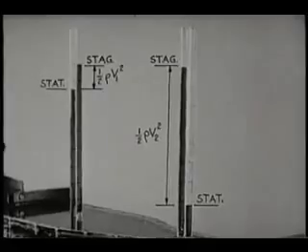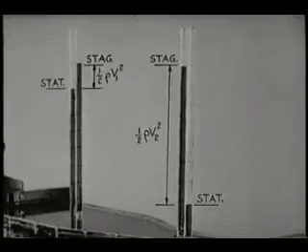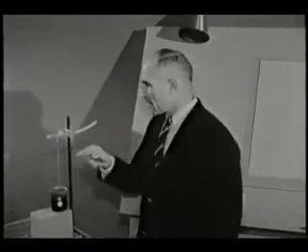Because of the area contraction, both the dynamic pressure and the static pressure change. But the sum of the two, the stagnation pressure, remains constant, which is what Bernoulli's integral told us. Bernoulli's integral also explains how we can produce suction by blowing.